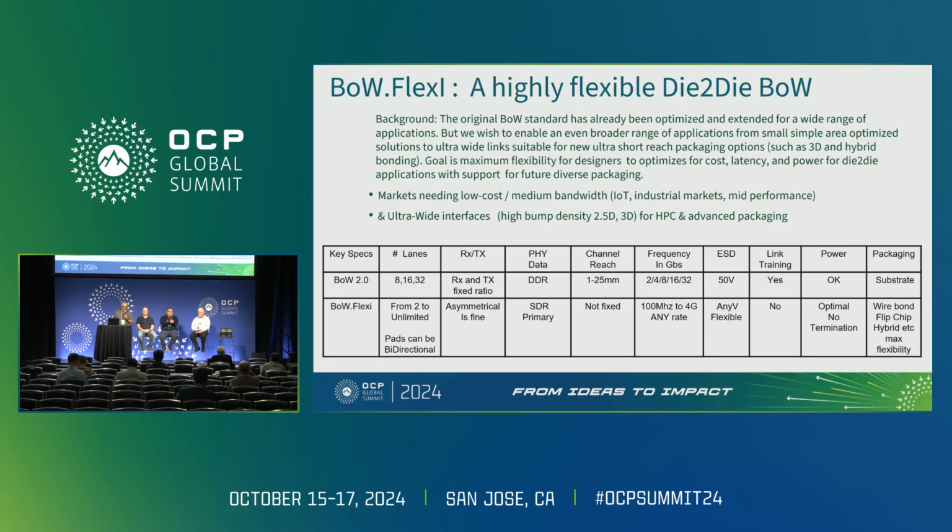And the final aspect of this is the ability to support different types of packaging. It may surprise some people in the high-performance compute market that there are actually people still using wire bonding. It is still the cheapest way of assembling die. It won't stop. And there are customers that are interested, for example, in just connecting to a die. So if you have an optical die, you can just wire bond to that directly, put your die very close together.